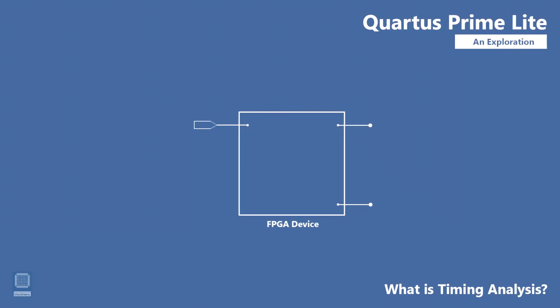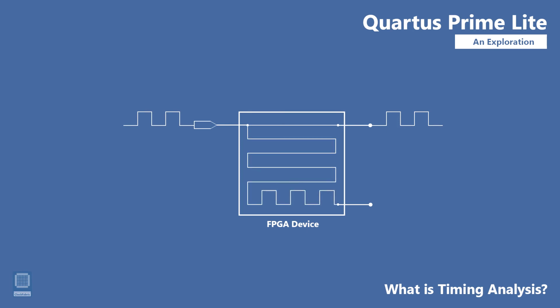So what is timing analysis and how does it affect our FPGA development process? FPGAs, by the nature of their complexity, are big in size and have many interconnected networks routed from end to end. So for example, if 2 clock signals start from one point and one signal goes out immediately to a signal pin and the other follows a more complex route and finally comes out of some other signal pin, then there is going to be a lag between those clock signals. This lag is due to the distance one of the clock signals had to traverse within the device itself.